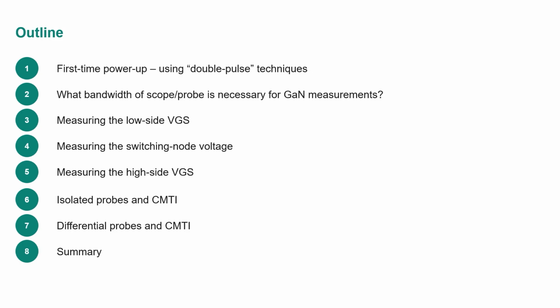lab. So I'm going to talk about the double pulse test technique that you can use to make sure everything is functional before you apply full power. I'm going to talk about the bandwidth of the probes and the oscilloscope system that you need in order to be able to accurately measure.